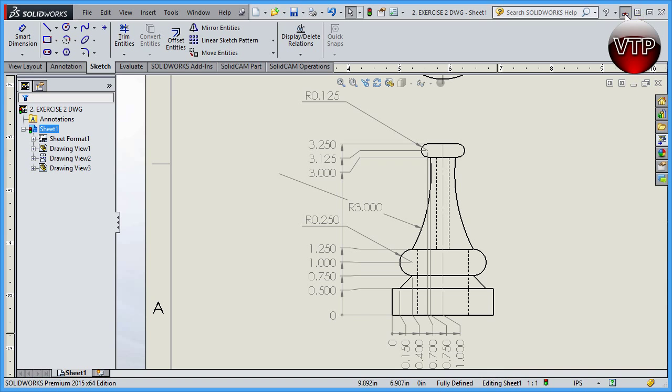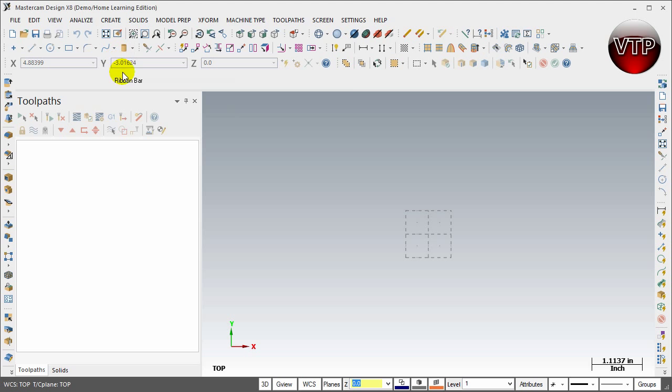So let's get started on that. I'm going to come over here and just make sure you start a new file. Make sure it's in 3D construction plane. Okay, we are drawing a geometry for 3D use. We're going to be making a model out of it. Okay, and then make sure Z is in 0.